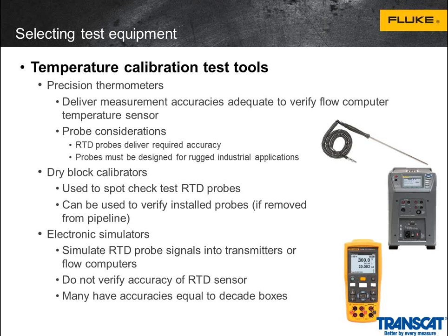Moving on to temperature calibration test tools, we're going to talk about 3 main types. The main one that people will use will be a precision thermometer. They basically will be a specialized tool, although some manufacturers have actually integrated a precision thermometer into an electronic pressure calibrator to make an all-in-one tool. They'll primarily use an RTD probe.